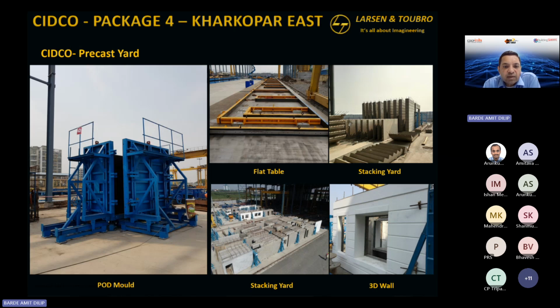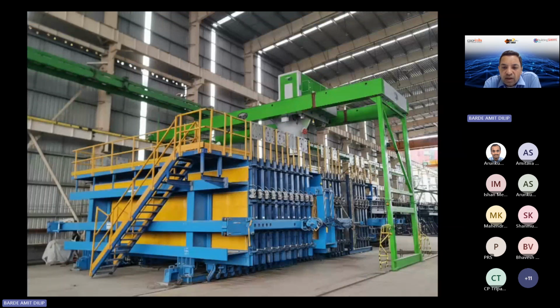We do a lot of work where most of it is done indigenously with in-house molds. But at the same time, if you remember, we talked about the mechanization we are doing. So in that new factory is one of India's first fully automatic battery molds. Right. So this is used for vertical casting. If you see these cells, if you see my pointer, they open up, you put your reinforcement cage ready and close the cell. It is hydraulically operated, has its own vibrator system and its own curing system. And then about 80 panels can get poured together.